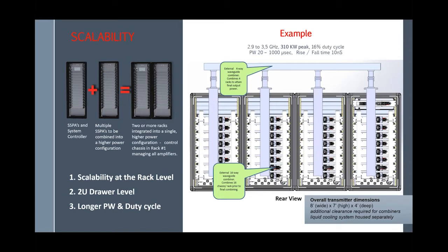And if I need to do, let's say, 2 milliseconds or 5 milliseconds pulse, there is another profile that will back off the peak power, so that's equivalent to the power dissipation that the device can handle. So I can have multiple profiles and control the amplifier that way, and you just call and say, I'm gonna run at 5 milliseconds pulse, and then the amplifier will adjust itself for that condition.